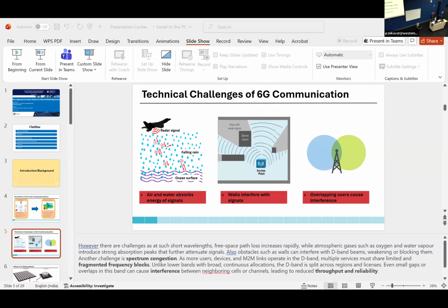So my study extends this, where I use PIN diodes to electrically tune the stop band with a reconfigurable band stop surface. Yet I focus more on the D band spectrum to help 6G communications, focusing on transverse electric and transverse magnetic normal modes using different meta-atom structures and materials. So using the